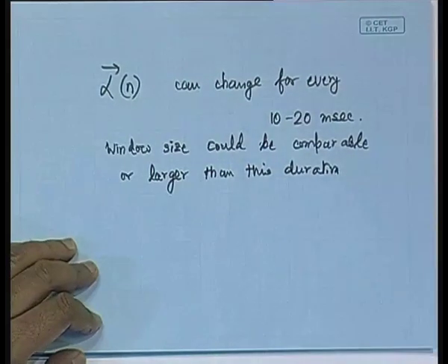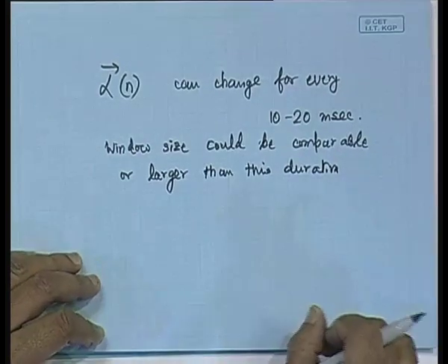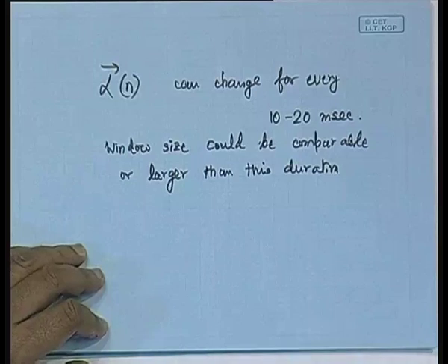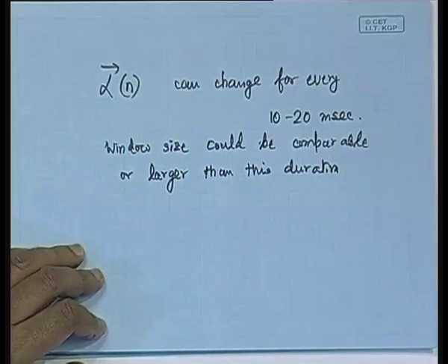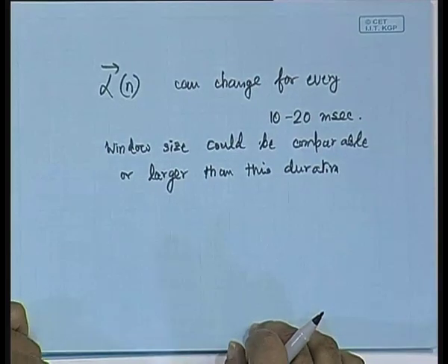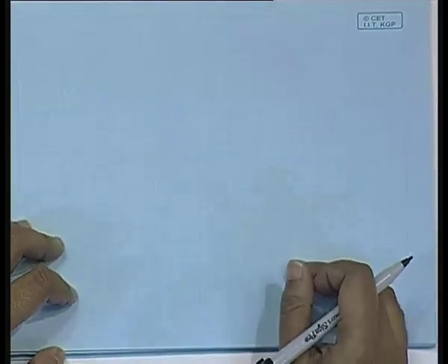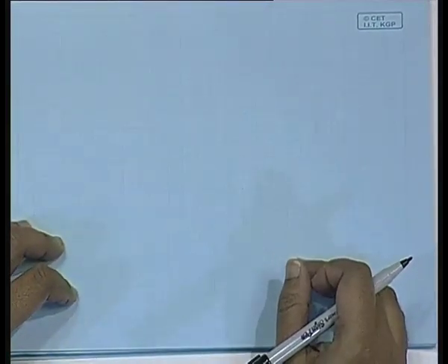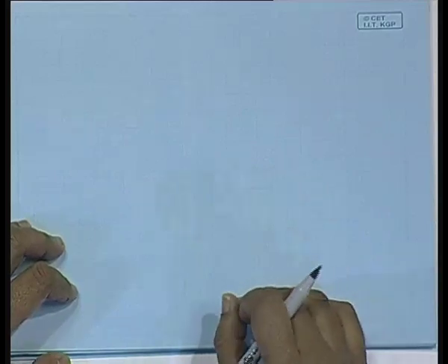Okay. So, now we can show some performance graphs, with the value of p, of how the adaptive predictor should improve, if at all, and to what extent it improves the predictor gain. So, we make a plot of the predictor gain GP versus the number of coefficients, and we will be plotting for two situations.